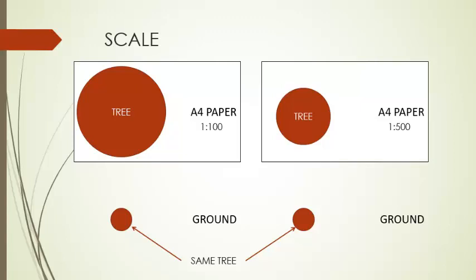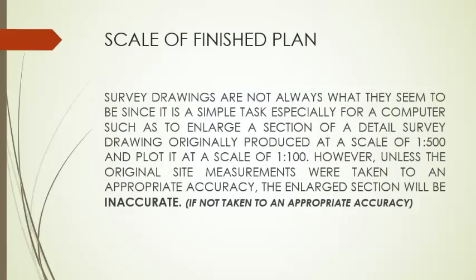Alright, next. Survey drawings are not always what they seem to be, since it is a simple task, especially for a computer, to enlarge a section of a detailed survey drawing originally produced at a scale of 1/500 and plot it at a scale of 1/100. However, unless the original site measurements were taken to an appropriate accuracy, the enlarged section will be inaccurate.